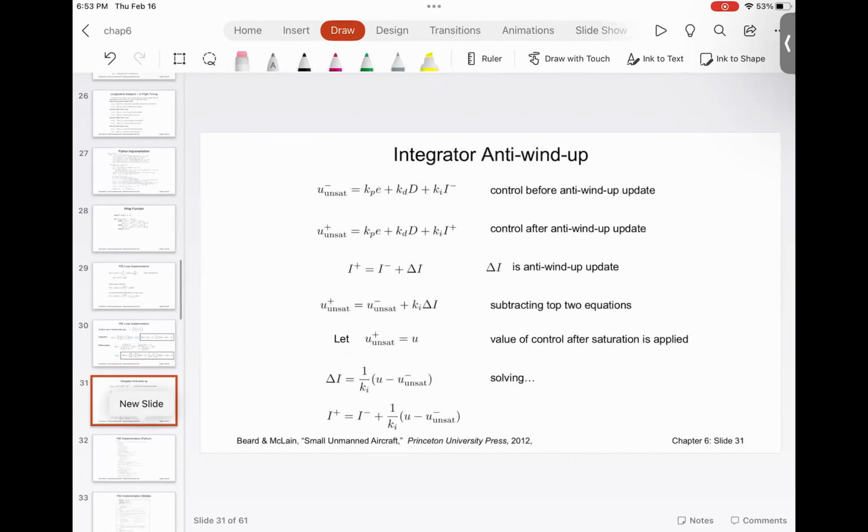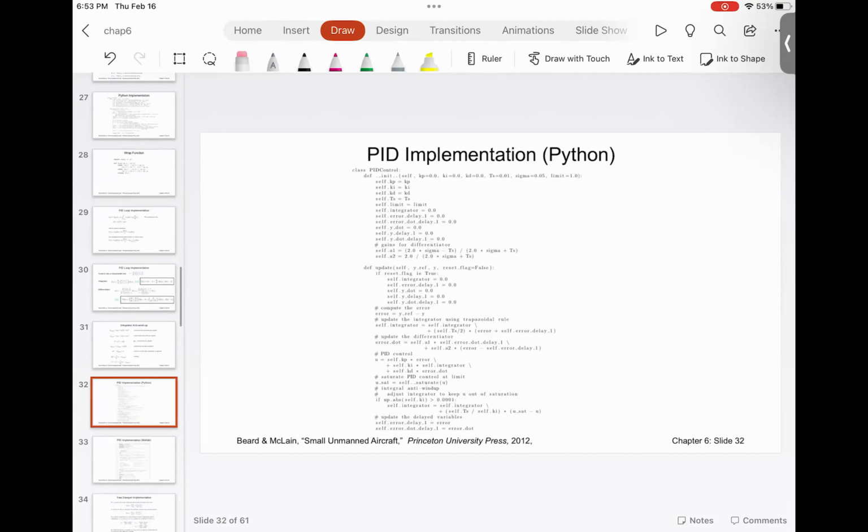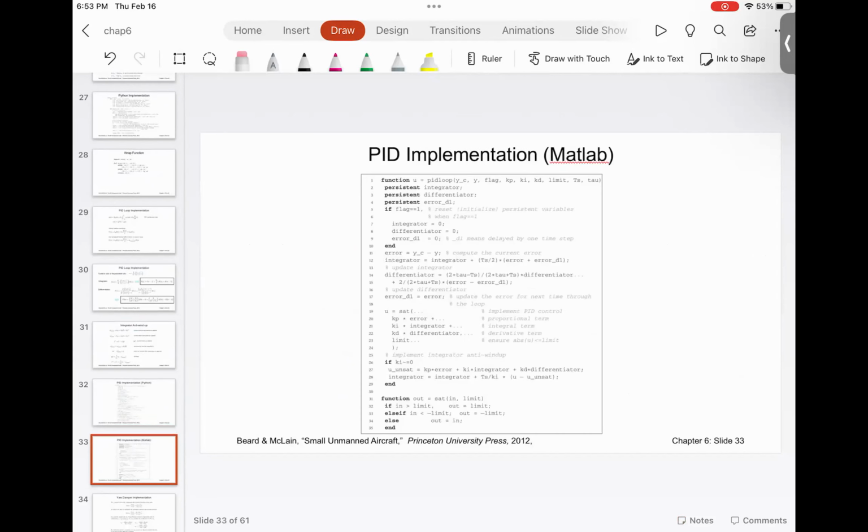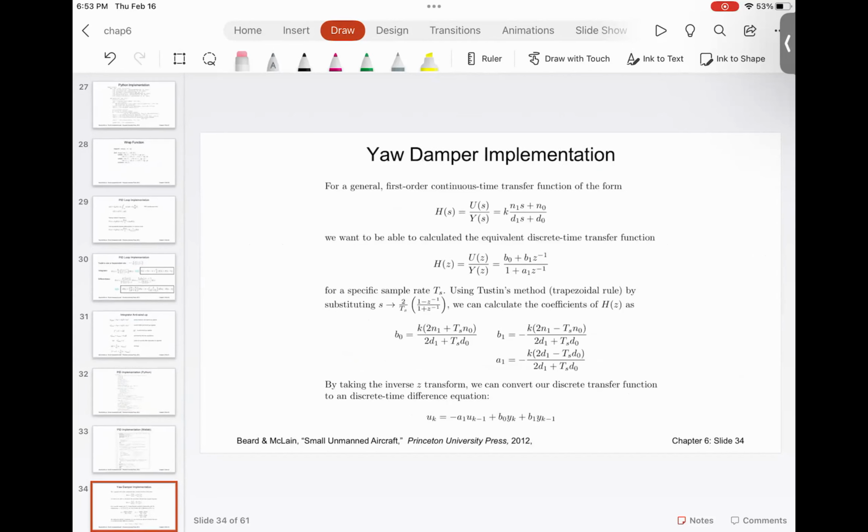I will show you the project, and I will talk about the implementations, because please understand, we are going to implement these control algorithms, or autopilot algorithms, on discrete hardware. The sensor data that is coming to us is in the discrete domain. It's digitized. So even though we have the equations for continuous transfer functions, you need to convert those into the discrete.